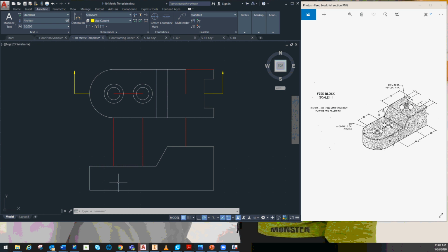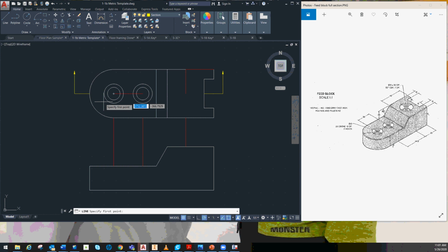So in our front view now, we're going to want to draw what we would see on the inside. So normally we would see our counterbores as hidden layers. They're going to be actual object layers now because it's cut open. So let's start drawing our counterbores here. I'm just going to extend this construction line just to give me some reference points to go across from here. Okay, so we're going to just bring this line down here, and we're going to start shaping out this counterbore. I'm in a construction layer meant to be object, but I'll change that after. So these are 10 units deep. And we'll just bring that across here, just like that.